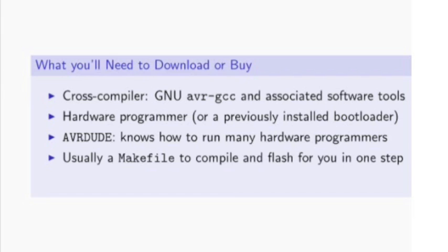It does all the grunt work of compiling a C program for your AVR for you. So you're going to find a makefile, and that's going to be new to the Arduino stuff, although Arduino has its own makefile that's just not exposed to you. You'll be able to find it, actually, if you look for it.